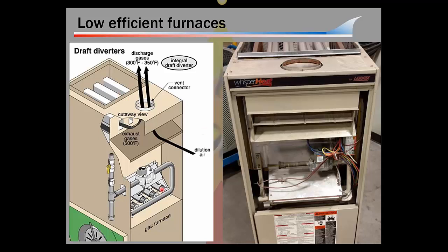Our high-efficient, mid-efficient furnaces, all of those burner gases mix together, okay? But here they don't mix until they get in with the dilution air, and if we measure here, we have a diluted sample that's not a real representation of what's going on in each of those burners. Does that make sense?